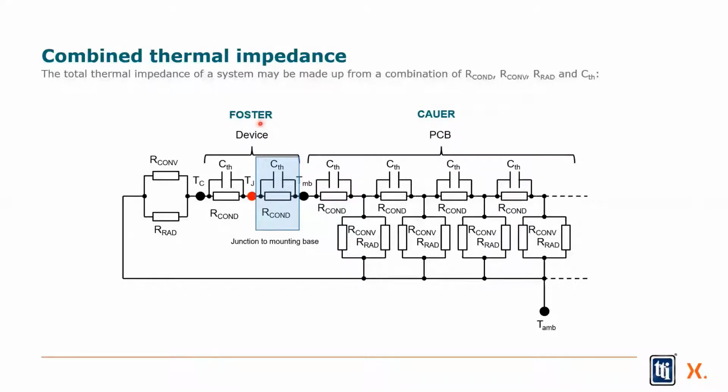Like I said, we'll provide the Foster models from Nexperia directly, the Cauer models for our parts, and then you can also get Cauer models from your heatsink supplier or your solder supplier. They have those values as well too. So let's look how we would actually do a simulation.